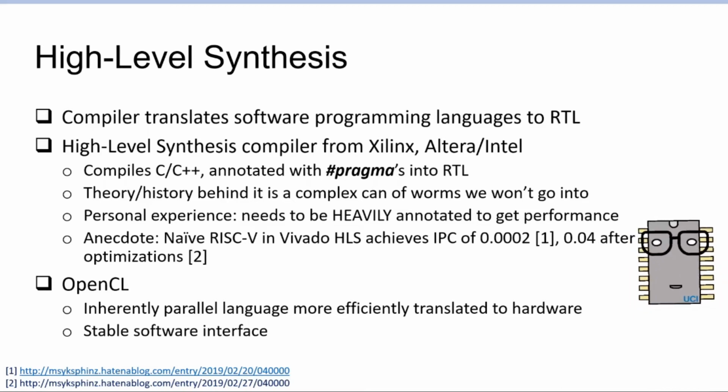But if you are dealing with very custom, very irregular kind of computation, the kind of stuff that FPGAs are typically very good for, the compilers seem to have a difficult time extracting the fine-grained parallelism from the low-level semantics of a language like C. They have trouble differentiating the intentions of the programmer and the restrictions put on it by the language.